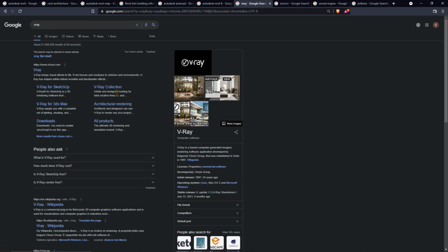So I'm going to stop for this first introductory lesson, but I also want to tell you that in Revit Lite, you won't have the part concerning the rendering, but rendering in Revit is a little bit heavy. I suggest you can export your scene into another software like SketchUp or Cinema 4D, some lighter application that will let you work with more realistic models and objects, and also with V-Ray as a plugin. So you can install the V-Ray plugin, and you will find videos and courses in the channel talking about V-Ray installation and how to use it in different software like Rhino, SketchUp, Cinema 4D, and so on.